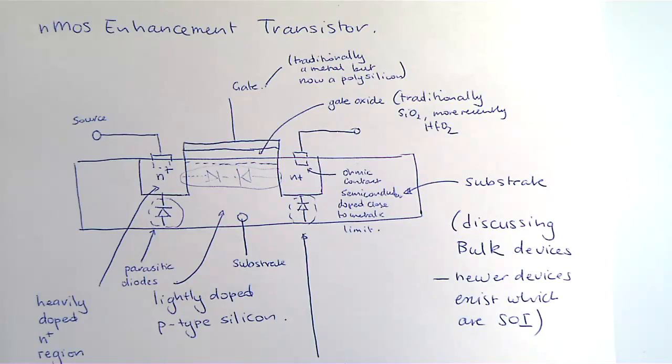All right, now we're going to make contacts. Okay, so we put an oxide here, we put a gate. Now, usually in the past it would be metal. These days, people use something called polysilicon. Okay, and you can think of it as an amorphous layer of silicon, which is very heavily doped, right? So it behaves like a metal, right? But it's not. It's polycrystalline rather than monocrystalline like here.